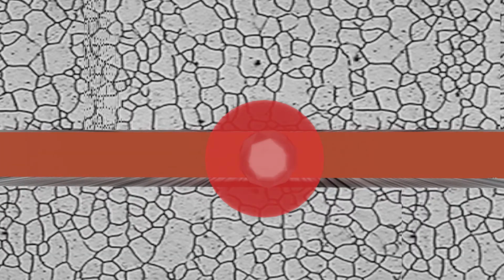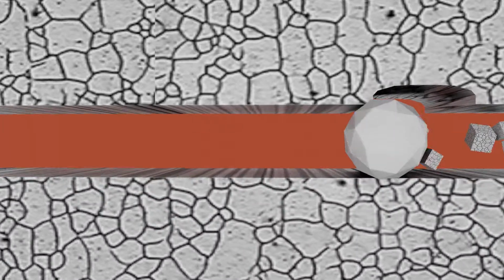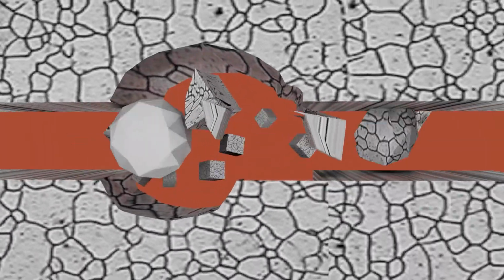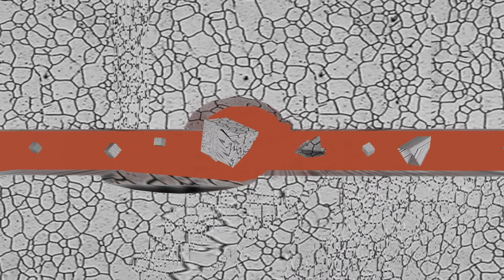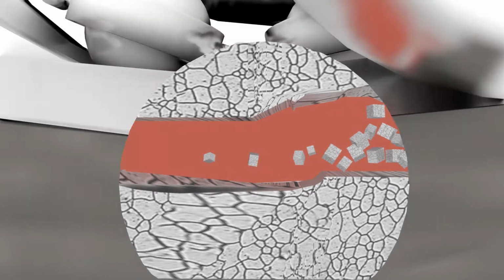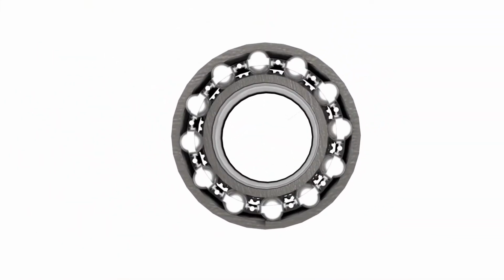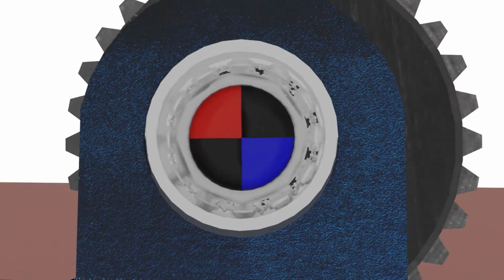He couldn't see as they were getting trapped and compressed under very high pressure between the sliding surfaces of his bearing, causing microabrasions and tiny cracks to form. He also couldn't see the chain reaction of wear as more and more particulate broke off, causing further cracks. And John also couldn't see as this erosion grew larger and larger, until the sliding surfaces of his bearings were no longer smooth, causing his bearing to vibrate violently.